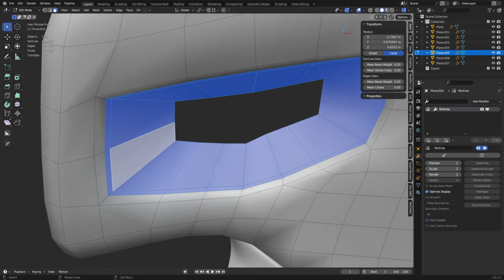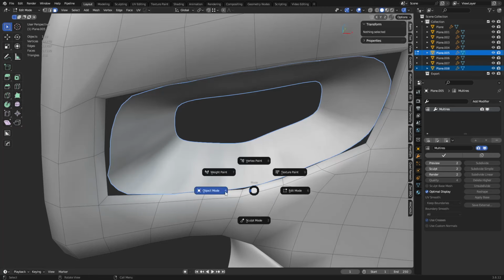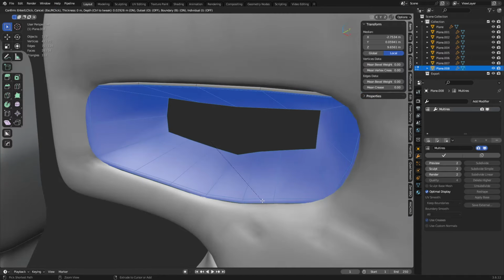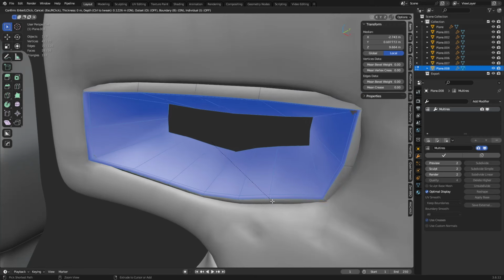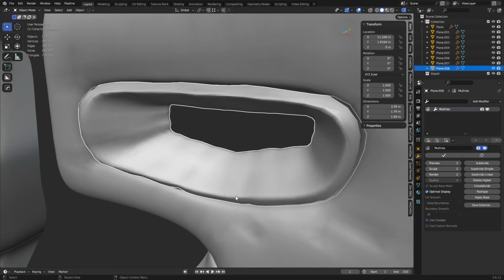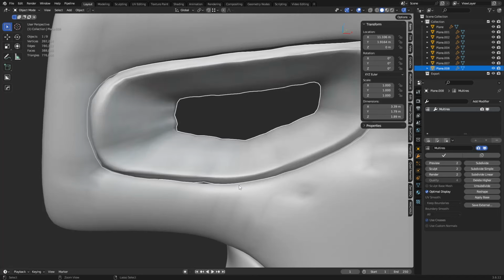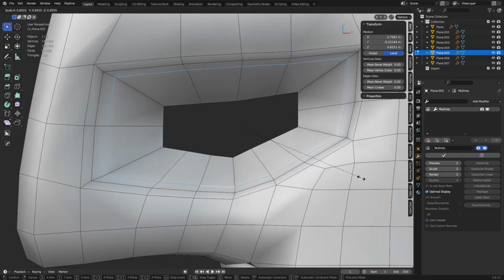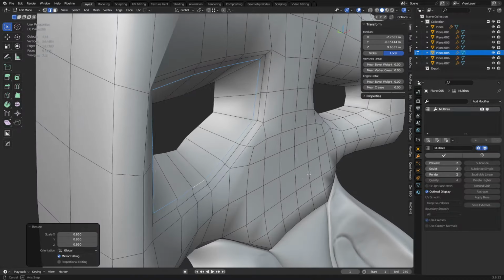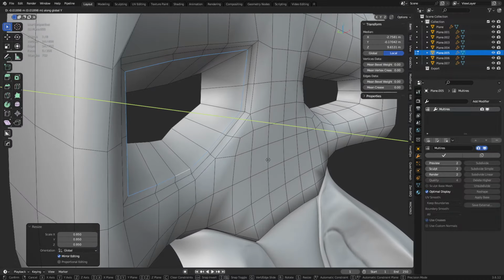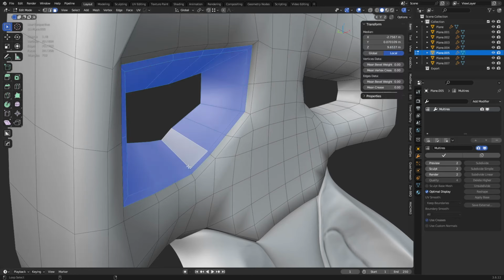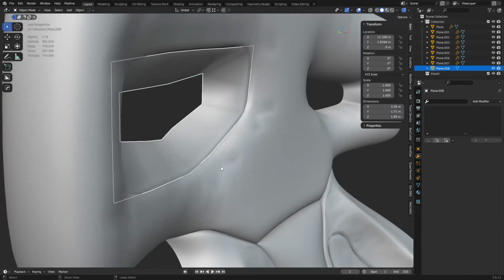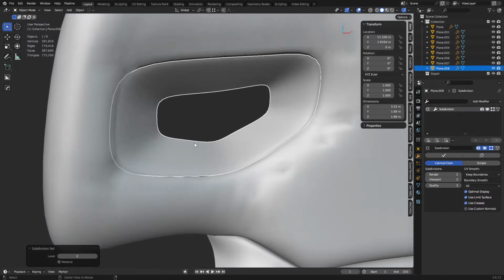And this whole element here, I'm going to grab it, press P and separate selection. Okay, and you can see what's going on here now. So if I want to inset and hold control, I should be able to push it out a little bit. Ooh, that's terrible. Actually, what's going on here with this one? Let me try scaling it in a little bit and see if that helps. Trying to get just a flat section here like this. I think the multi-res on it is messing it up. We'll just use a subdivision on this one. All right.